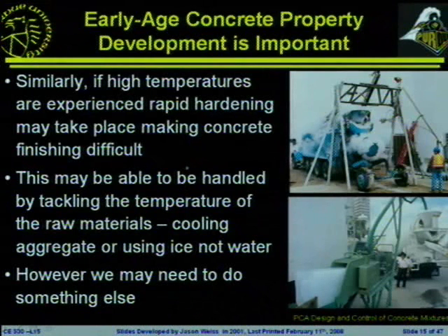Similarly, though, if concrete is too hot, it's going to set too quickly, and we're not going to have time to place that concrete. So you'll see, especially in very warm weather regions, them putting dry ice into the back of a truck to cool down the overall materials, or actually replacing the water in the system with ice so that they can cool down the overall temperature of the mixture, keeping the aggregate saturated.